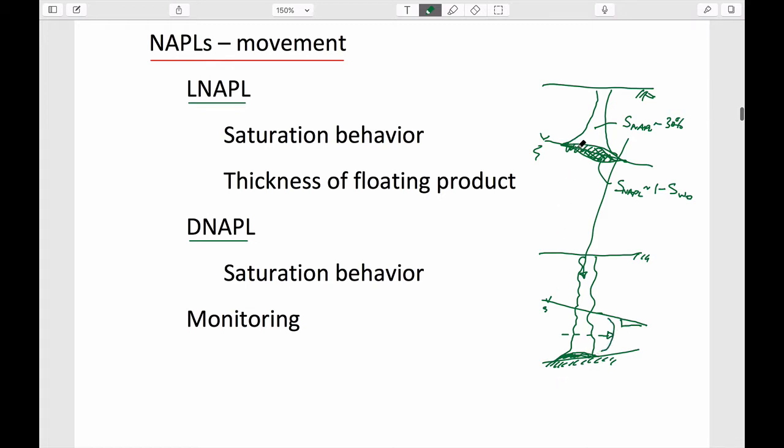And we know that the mechanism by which this high NAPL saturation component has been arrested hasn't been by the water table, which it has slipped right through, but it's being arrested by this capillary barrier. And so this is the reason that it stops at this particular location and would rest in place.